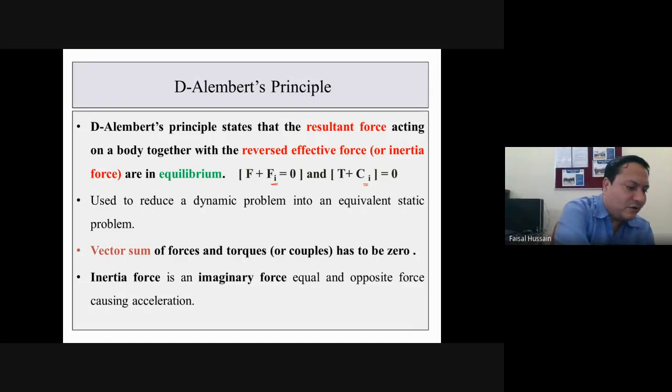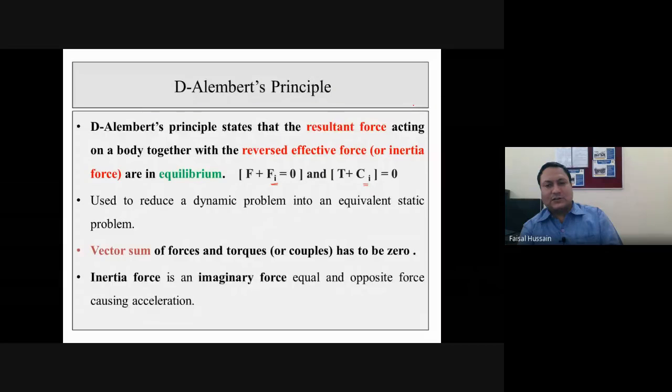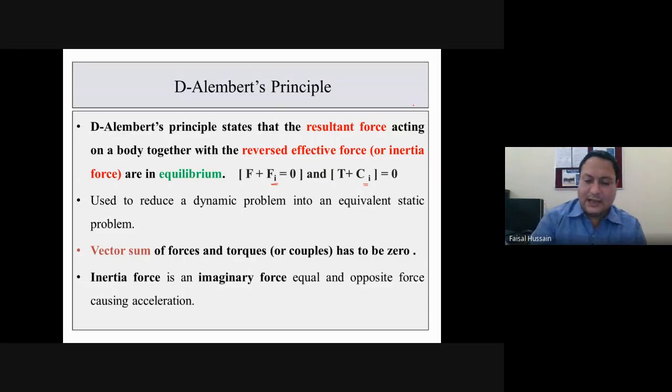And I already have told you the effect of inertia forces is considered in dynamic force analysis condition. And what is inertia force? Just an imaginary force which is equal and opposite force which is causing the acceleration. Okay. Accelerating force and inertia force are the same but opposite in direction. If the accelerating force is moving towards right, inertia force will move toward left.